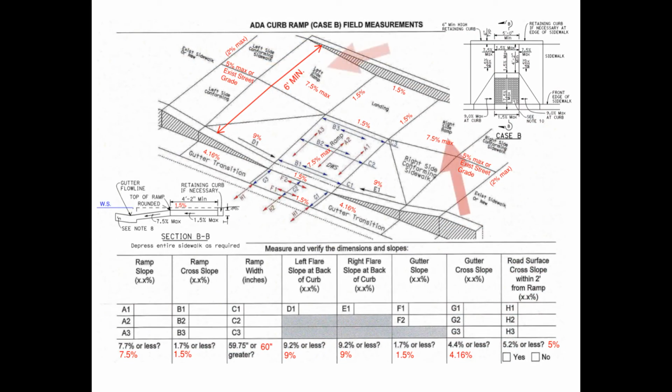Now the question has come up on a Case B ramp. The ramp right and left, as noted per Caltrans grading sheet, represents this to be a ramp. These ramps are required to construct as part of the Case B ramp itself. I believe this could be considered a perpendicular running slope of a ramp, and the 15-foot rule for these ramps would be acceptable if needed. Please consult your Americans with Disabilities specialist before constructing or designing this type of ramp using the 15-foot maximum as a guideline.